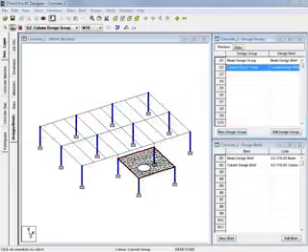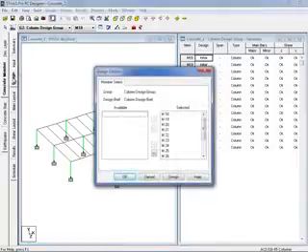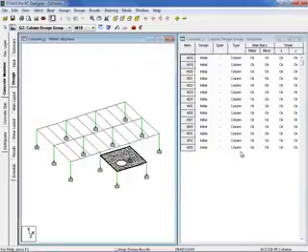To initiate the design of the concrete columns, I would want to go over to the page control area and select the Concrete Member tab, followed by the Design sub-tab. When I do that, automatically the Design Options dialog will appear, and all of the members within this column design group will automatically be selected. To start the design, I can go ahead and click on this Design button, and then you can see that all of the columns have been designed. I didn't get any warning messages, and all the designs are indicating that some main bars and shear reinforcing results have been obtained.